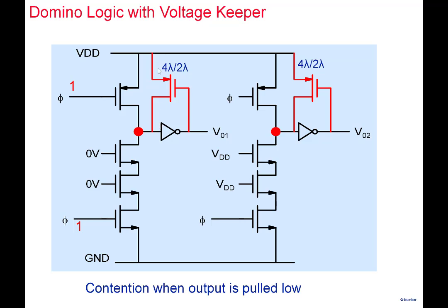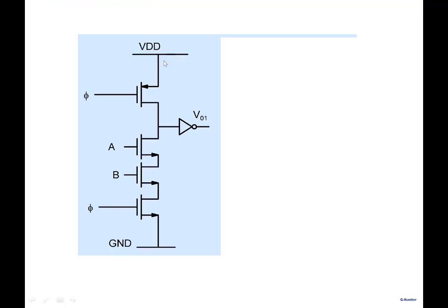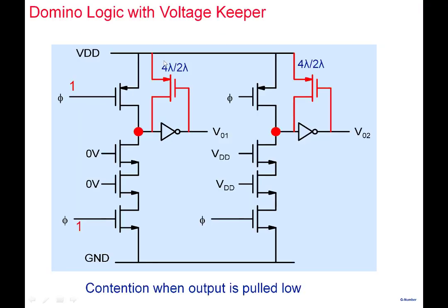So it's a viable way of doing it, and it is considered one of the fastest ways of implementing logic. The capacitance at the nodes is not very high. All that you get is a contribution from one single PMOS, as compared to a regular fully complementary CMOS, which gets contributions from a lot more transistors here.